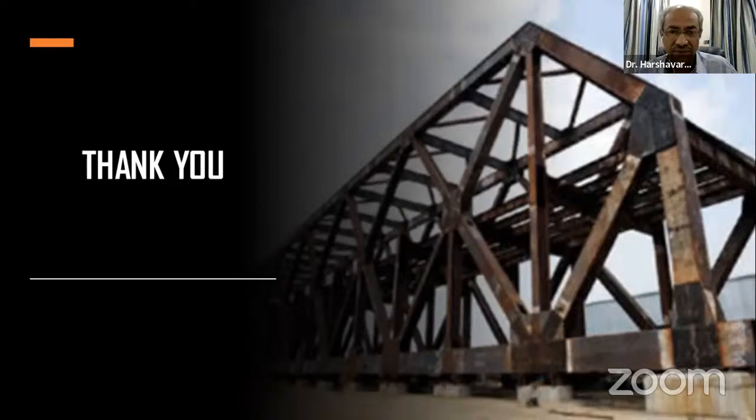I know of a case in which we were somewhat involved as checking consultants, in which the stainless steel girder was distorted quite heavily. Now I can understand why, because duplex stainless steel was used rather than 304. In using that, I think there was a problem in the welding, and all the girders actually distorted and we had to reject them all. So that was stainless steel for live load with a road deck, and we had to reject them.